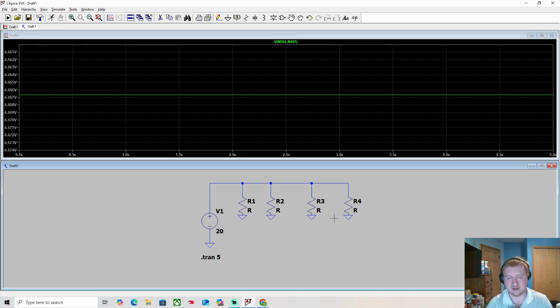But anyway, sometimes you don't want certain ground planes to mix together. It's just important to know that depending on the signal type and whatnot, you may not want to have the same ground reference for signal versus power. That's a big no-no sometimes.